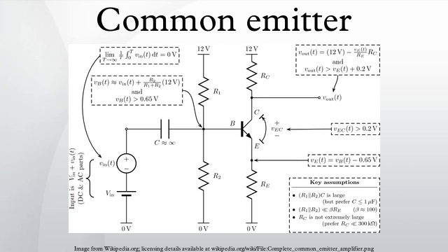The common emitter circuit is the most widely used of junction transistor amplifiers. As compared with the common base connection, it has higher input impedance and lower output impedance. A single power supply is easily used for biasing. In addition, higher voltage and power gains are usually obtained for common emitter operation. Current gain in the common emitter circuit is obtained from the base and the collector circuit currents. Because a very small change in base current produces a large change in collector current, the current gain is always greater than unity for the common emitter circuit. A typical value is about 50.